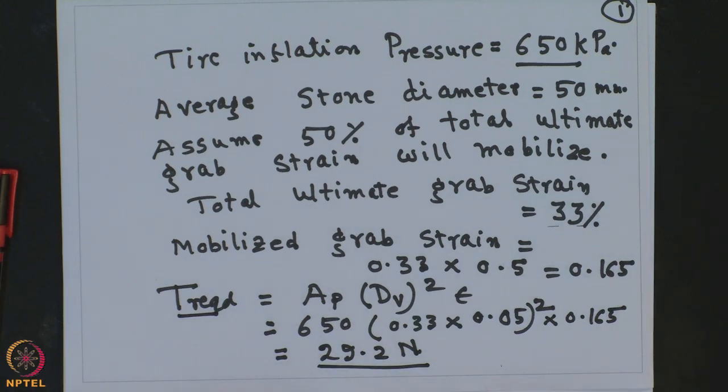So, here I have shown you some specimen calculation and theory based on your burst strength as well as the grab strength. Burst strength is very important for different types of projects where the geotextile or the geomembrane material may burst. So, you should know what burst strength is required and what kind of geosynthetic material you should select for that specific application.